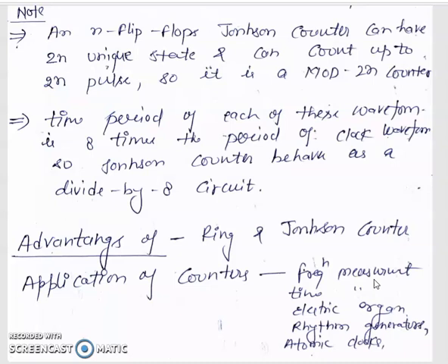In case of the ring counter, each state frequency is equivalent to ft, the total frequency, divided by n. N is the number of bits used in this counter. And finally, the each state frequency of the Johnson counter or twisted counter is equivalent to the total frequency ft divided by 2n, because in the Johnson counter we have 2n states or modes, n is the number of bits.